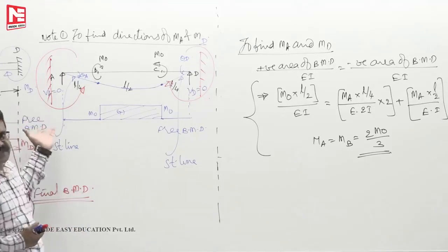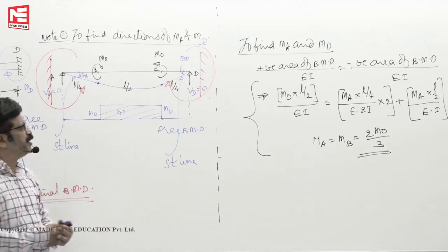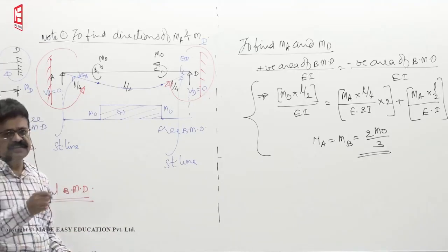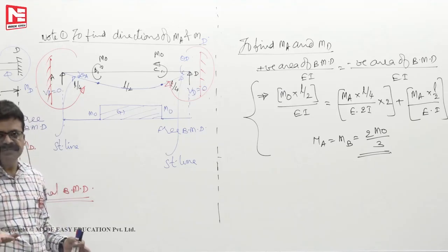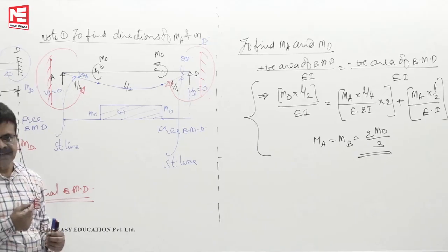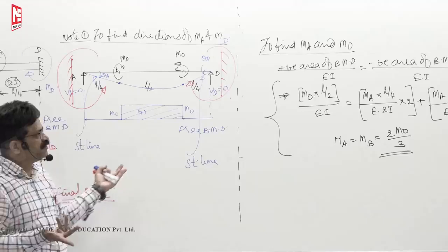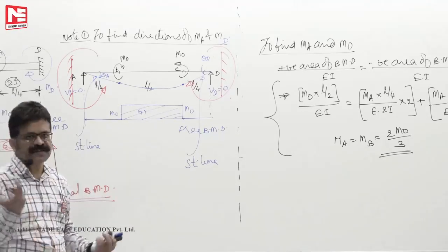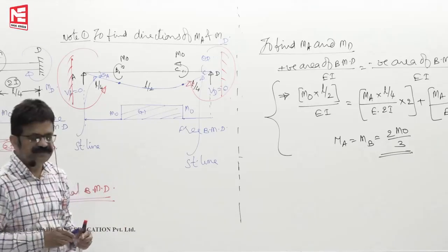So this is a simple case. Quickly we should draw such bending moment diagrams. We should not think about the bending moment at the RHS of D, LHS of D, that story you write for SM. Having understood that, next time when you are doing it by inspection itself, you should be able to draw the bending moment diagrams. Otherwise, if drawing the bending moment diagram itself takes 10 minutes, then where is the question of finding the positive area, negative area, within 1 minute? Impossible.